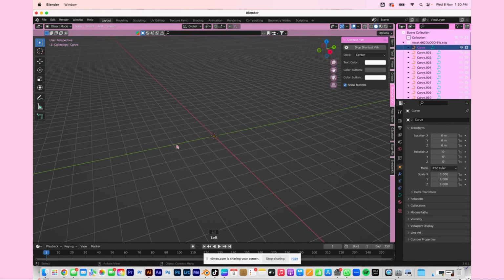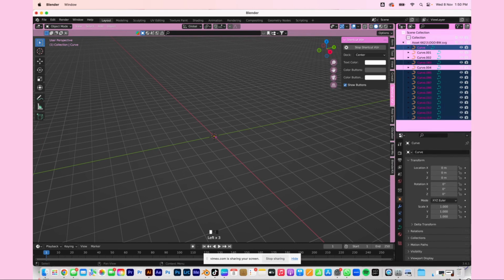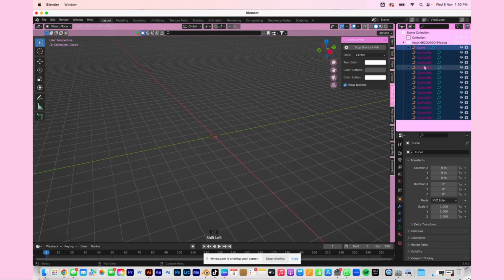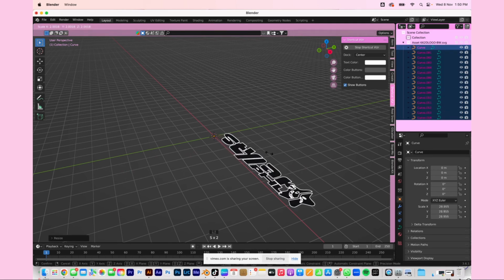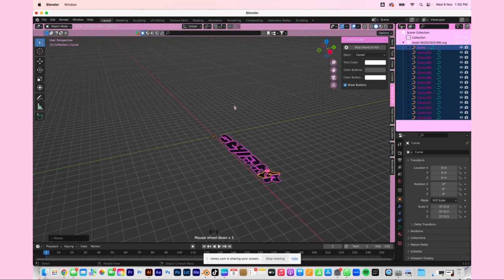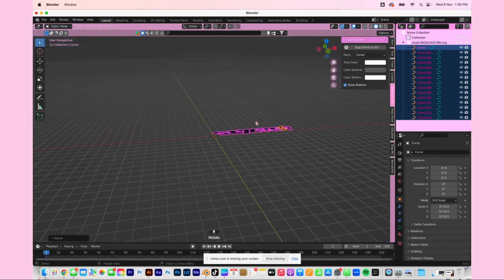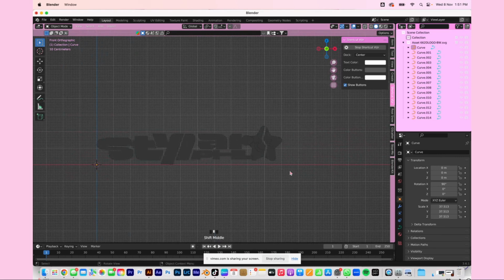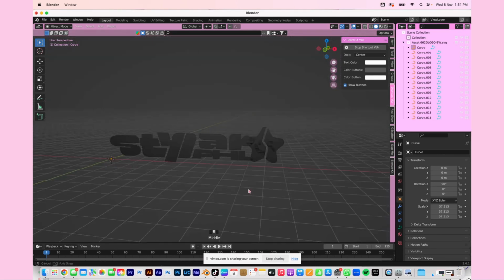Now you can either drag like this, but as you can see, sometimes you don't grab all the files, so you can just shift and select all these elements and then press S and enlarge. And now to flip it straight, I'm gonna click on R X 90, and I'm gonna press 1 on my numpad to put camera view like in the front.